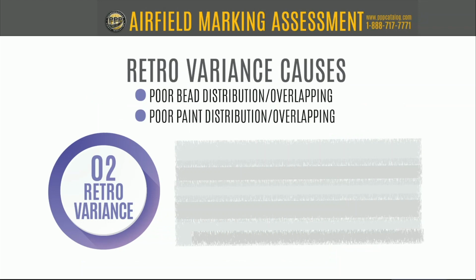Yeah, so one of the fixes that we've toyed with is where we'll have the inner tips of a gang of guns be these architectural tips because they're designed to overlap. And then the edge guns actually have the pavement marking tips, which you identified as a yellow tip, which is correct in the Graco, and I think it might be red on Titan. What that does is that creates a more even overlapping.